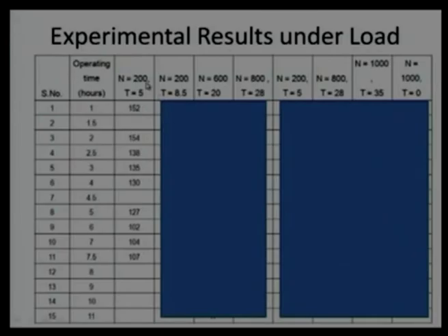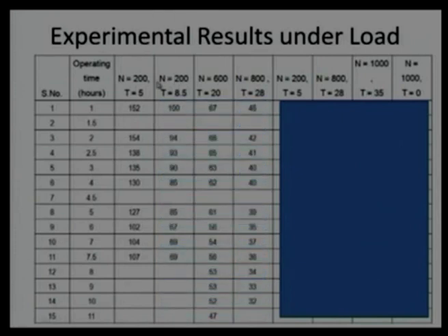Say at rpm 200, torque applied load is 5 Newton meter, wear rate or number of particles at the ppm level is continuously decreasing, from 152, 154 coming to 107. Of course, 2-3 ppm I am assuming is inaccuracy, or it is not giving that reliable results. Now, if I increase the load, what is going to happen? See, I am increasing the load from 107, it is coming down to 100 and continuously decreasing to 69. That means load is working,